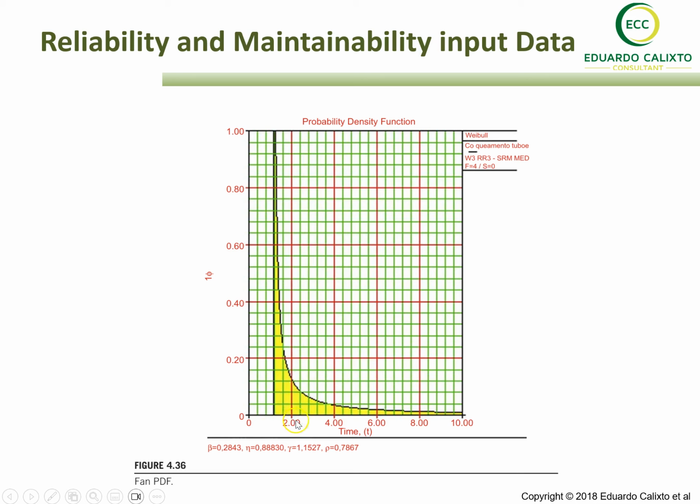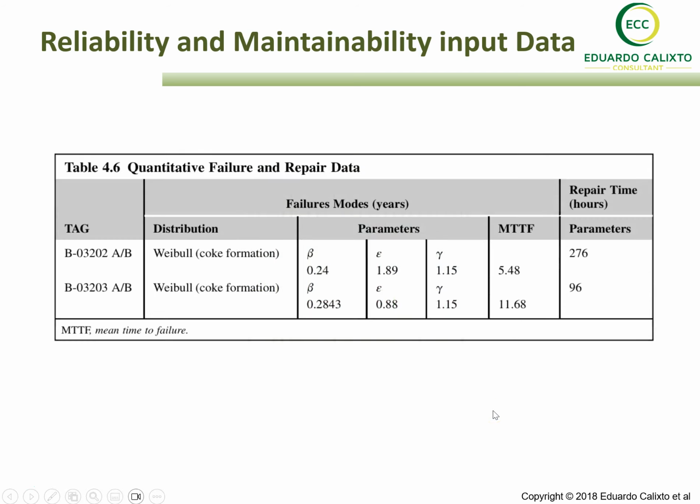What happened in this furnace was coke formation during high temperature, and also because they input some heavy oil in this distillation plant, and that was the reason found by doing the root cause analysis. After that we needed to change the material in these furnaces, and this was one of the critical equipment that we'll see later on.